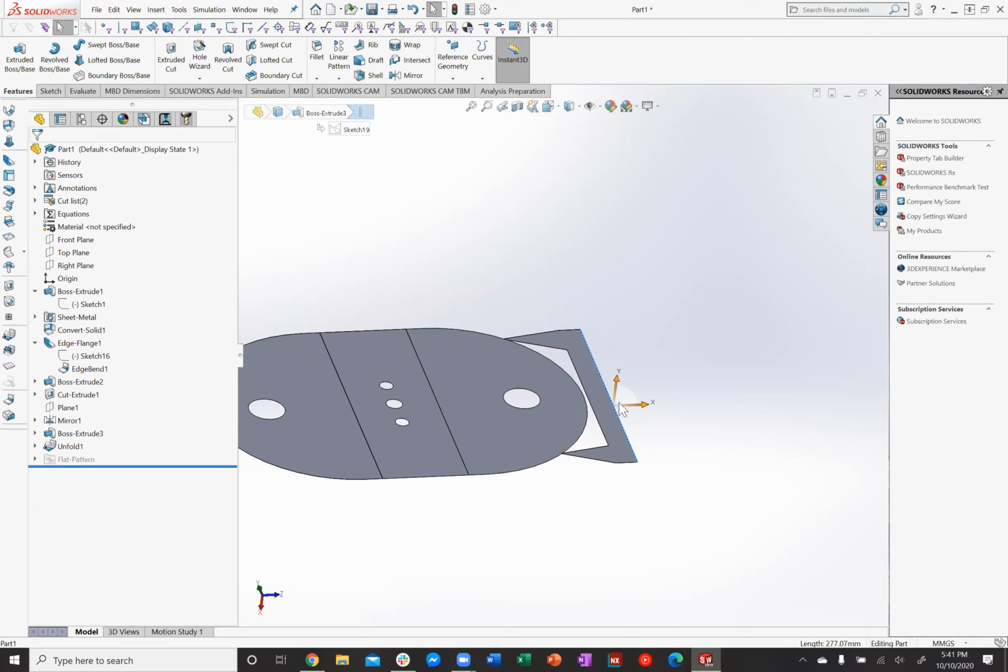You have this reference, and then the point of this is where it bends. And this is more common in my type of work. The machines that we have, this piece doesn't have to be parallel to the edge flange, because we have more advanced machines where the backstop can be angled.